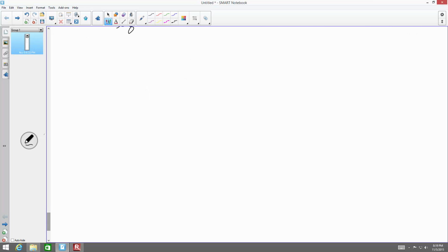So you've got a flexible pavement, and you've got a surface course that's 2 inches, has a structural number of 0.44. You've got an aggregate base that's 4 inches, has a structural number of 0.25.